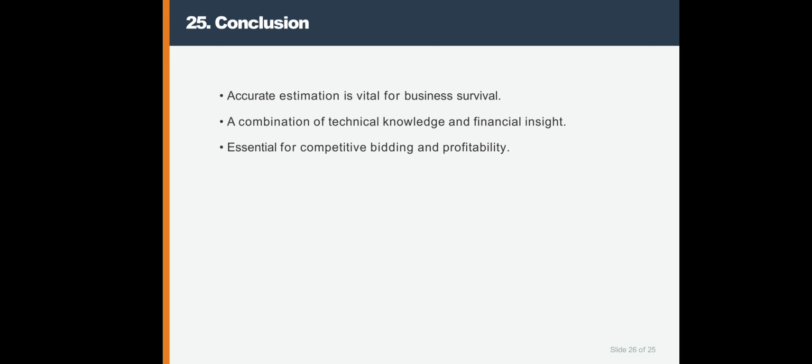The importance, aims, functions and procedure of cost estimation are discussed in this unit. The two types of cost estimates are preliminary estimate and final cost estimate. The three commonly used methods of costing are conference method, comparison method, and detailed analysis method. The essentials of competitive bidding and profitability are very important.